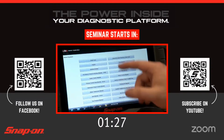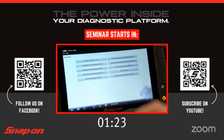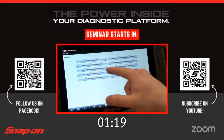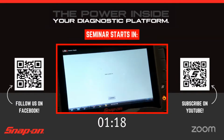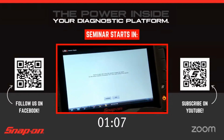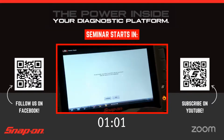This functional test is inside the engine, so we'll go in there, and then it's under functional tests. And you see it right there, fuel injector quantity adjustment. So we'll click on that. The ignition's already on, so we'll just hit continue. It says use the 10-digit code on top of the injector to program the injector. Do not confuse characters, for example, 8 and B, D and 0, when reading off the injectors. I already wrote down the code on the one that's in there, so we'll hit continue.